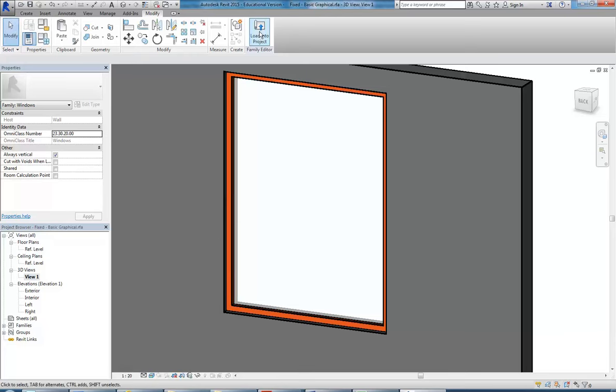The sides should still be locked. Oh no, sometimes you lose that as well, so it's no problem to just use align, side first, and the thing you want locked to it, and then the other side, and again, the thing you want locked. Right, so the ability to do those things is actually one of the main selling points of Revit over something like ArchiCAD. ArchiCAD gives you options like this, but with ArchiCAD you have to use a scripting language to do these things. But Revit has the ability to make parameters and things like that graphically. So in other words, you're drawing the elements that you want to be adjustable.